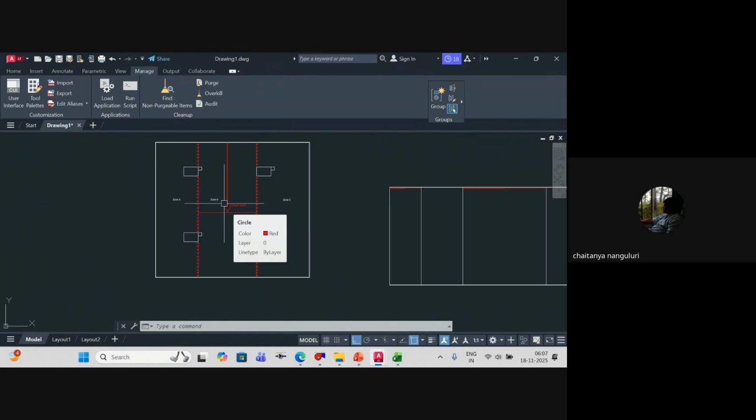So what you do is basically, for your fire pump, you will be selecting for the total one only. Understood? Suppose here we have three zones. If there is a fire in zone B, obviously both the water curtains will operate. Whenever there is a fire alarm inside your basement system, after more than two detectors or anything detects fire, it will be integrated to this automatically, so the deluge valve will open.